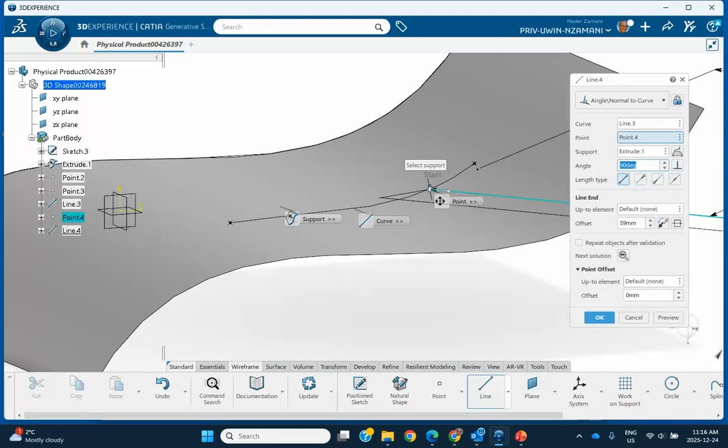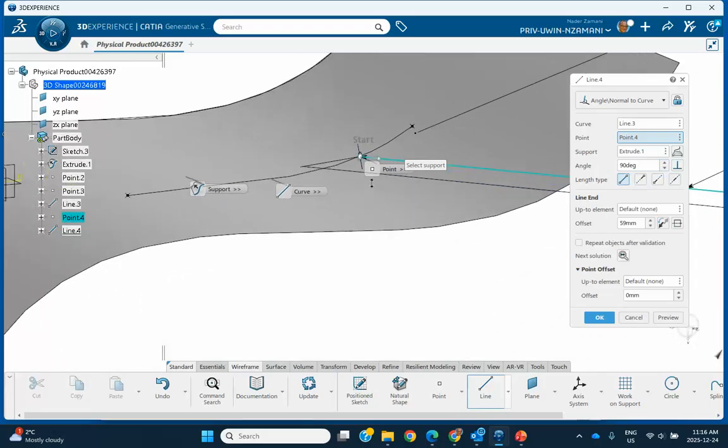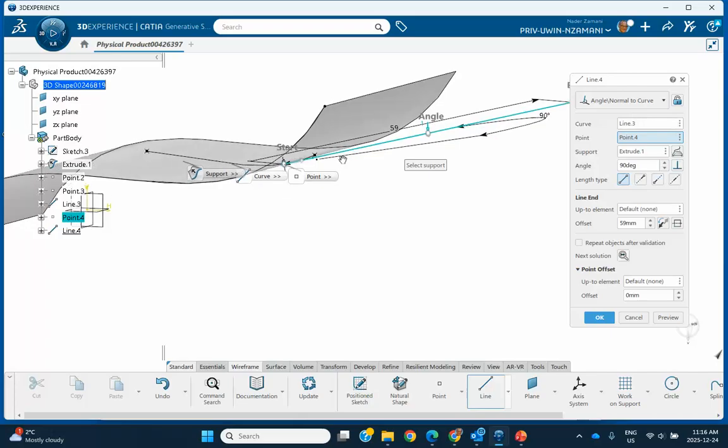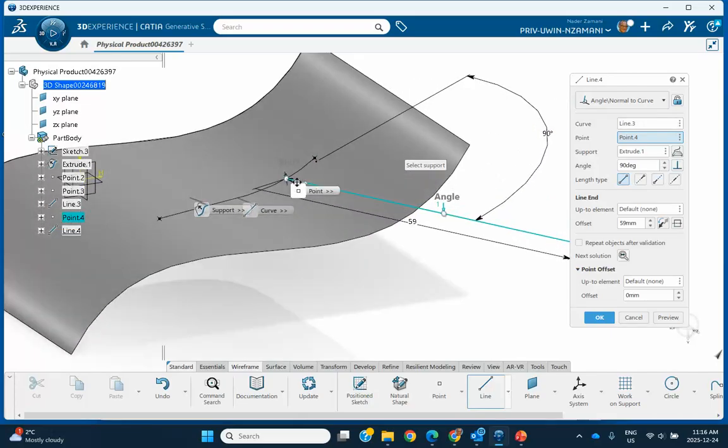And notice what it did. Immediately it drew that line for me. See that? So what's happening here is that when you select a point on that curve, immediately it draws a tangent plane, the tangent plane to that surface that is unique at that location. And essentially, we're back to square one.